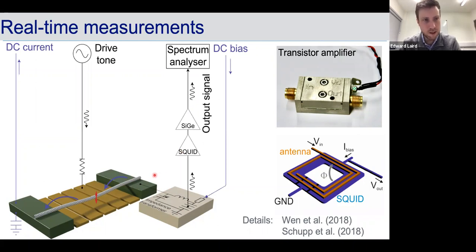So using all of this, the key point is that the output signal here, the one that contains the most interesting information, is a voltage that is going to be proportional to the instantaneous displacement of the resonator. So any resonance or oscillation here, we expect to be able to see in the output voltage.